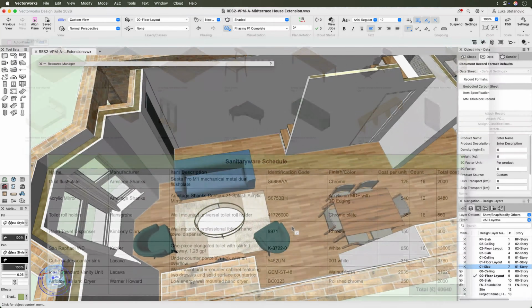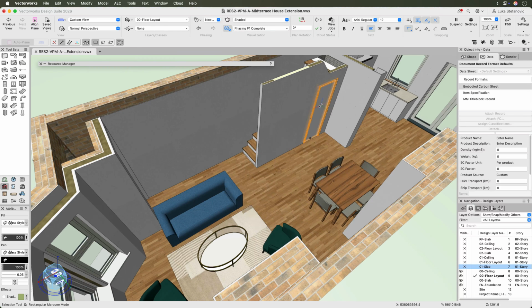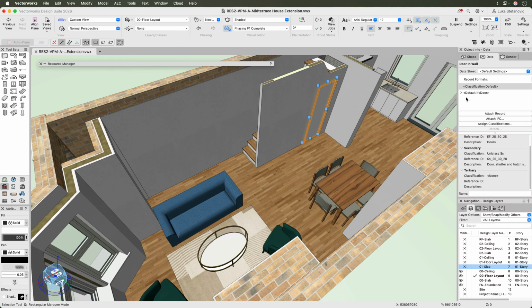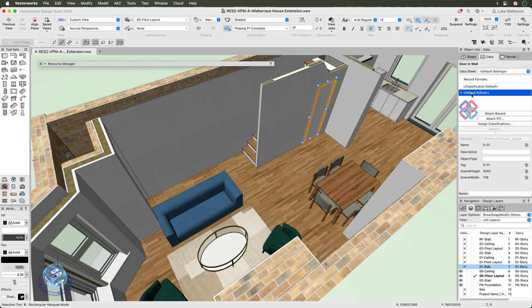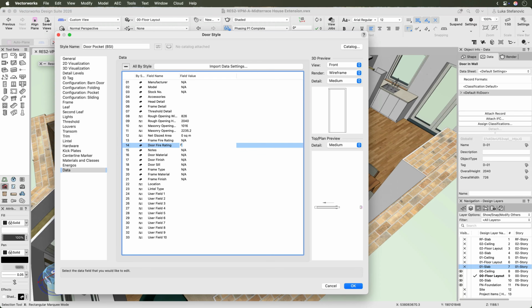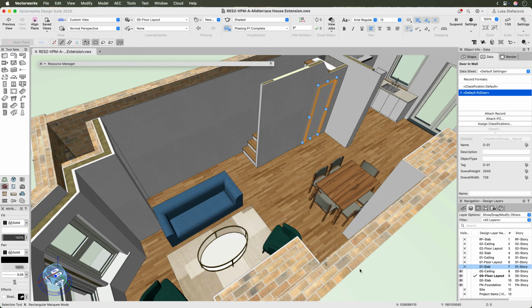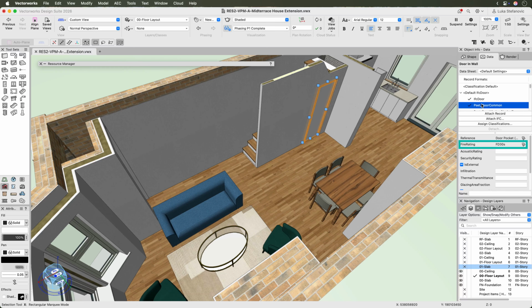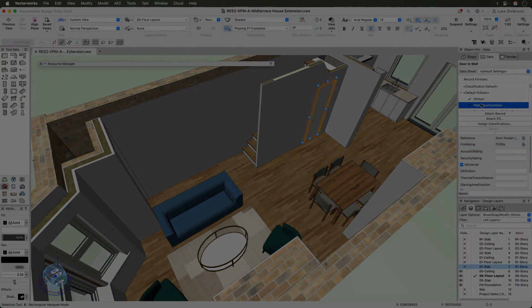Now, if you're working on a BIM project that requires some information standards like ISO 19650, these record formats are called IFC, and Vectorworks assigns them by default to most objects. A door will know it's a door, and a wall will know it's a wall. So to add data about a door's fire rating, you need to enter it in the correct place, and Vectorworks does the rest automatically and maps it out to the standard place your BIM coordinator will be looking for it.